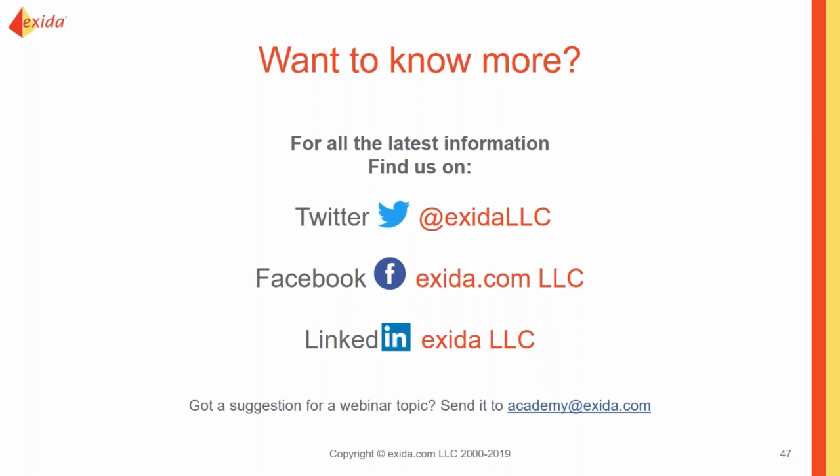That's fine. What I think you're getting at is that risk reduction when I said you had to bump up to the next level. Whenever you calculate your risk reduction for each CIF needed, that's when you need to say either, I am a SIL 2 with at least this risk reduction, or a SIL 3. But if you're talking generally in your facility, you can have all your SIL 1 CIFs be SIL 1, all your SIL 2 CIFs be SIL 2, because you're not going to have a SIL for the entire CIF.